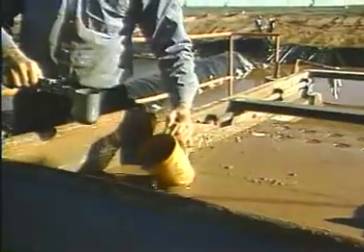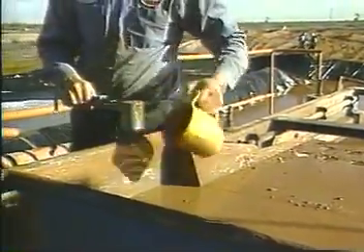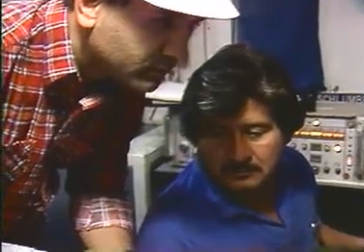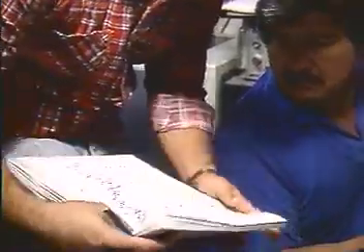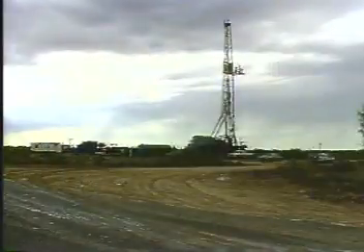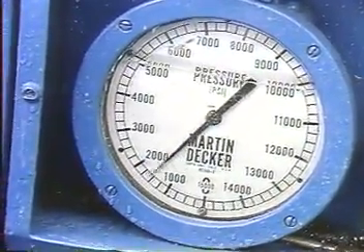Use a cement slurry as heavy or heavier than the drilling fluid to keep cement in place in the annulus. Be certain to select the correct classification of cement depending on hole conditions and strength requirements. Calculate slurry volumes using a caliper log and increase by an appropriate safety factor to avoid under-cementing. Pump plugs before and after the cement to ensure proper displacement. Maintain tension in the string while the cement sets. And remember to pressure test the cement job prior to drilling out or perforating.